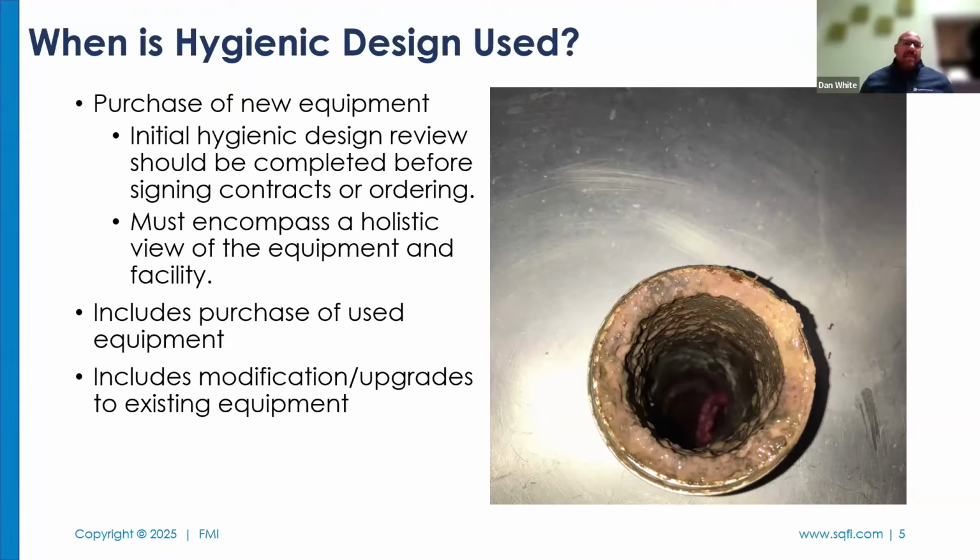Number one, when it comes down to equipment sourcing, not choosing trusted vendors. It is way cheaper for you to buy a tank off the internet. However, by the time it gets shipped to America on a crate, on a pallet, you can't inspect that tank. And I've lost count of how many times I've seen new pieces of equipment come into facilities where the welds were bad. They weren't made of the stainless that they quoted. So that's one: from the new equipment standpoint, it's sourcing equipment without validation of the quality of that equipment.